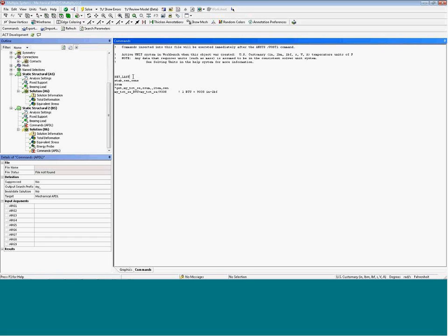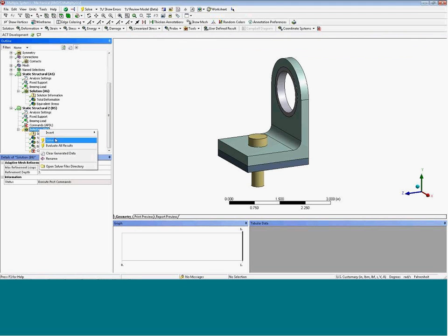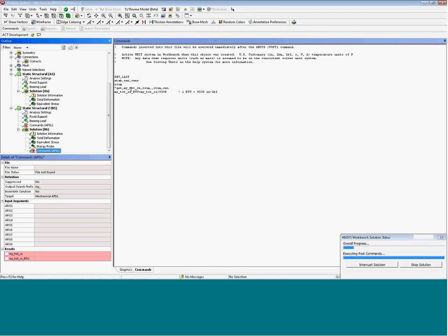The first thing we need to do when we're in there is read in a set of results that we're interested in. So I make an element table of all the elements for strain energy. I sum up that element table, and then I get the sum from that, and I store that as a parameter here.